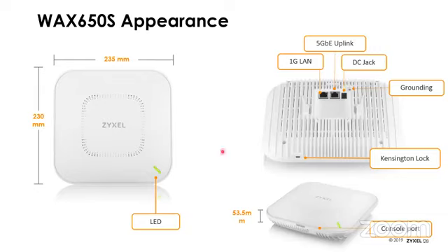So you can see here's the design. Now, this particular model, because of how heavy duty it is, requires an 802.3bt PoE or an AC power adapter in order to operate at full speed. It will still work with an 802.3at PoE source, but it'll operate at half speed because there's not enough power to run it at full speed. So that's something to keep in mind there.